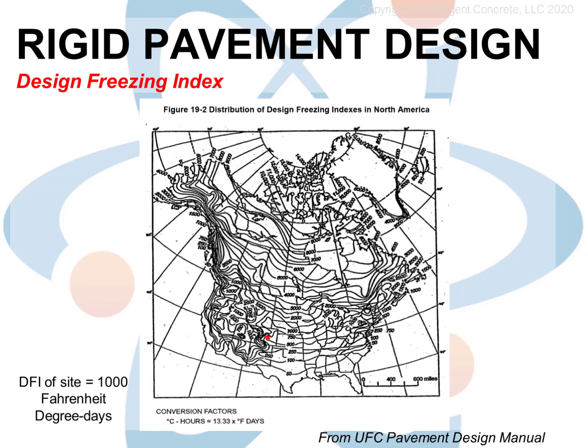This is a typical design chart prepared by the government by agencies like NOAA, the Corps of Engineers, and others using meteorological observations, extrapolations, and scientific judgments. For the Air Force Academy in Colorado, the design freezing index is 1,000 Fahrenheit degree days. There are also Celsius degree days, which are used in exactly the same manner.